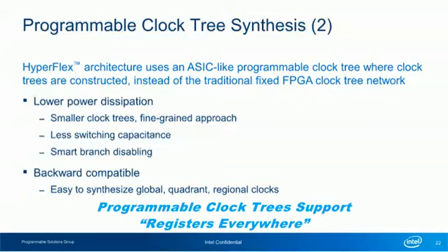Also, though our architecture diagrams show the routing channels between the ALMs, the physical FPGA is made up of layers in silicon. So rather than the routing channels being between ALMs, the routing channels, including the clocks, actually run over top of the ALMs as well as the hyperregisters. So it was not necessary to expand the clock tree to connect to these additional hyperregisters.